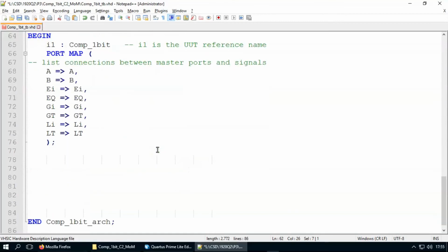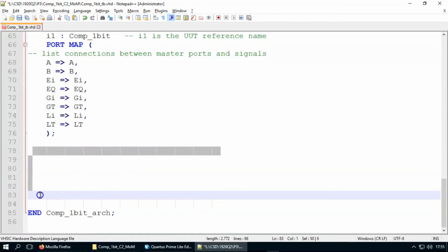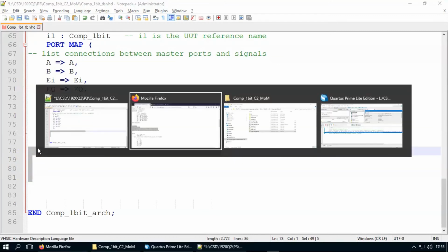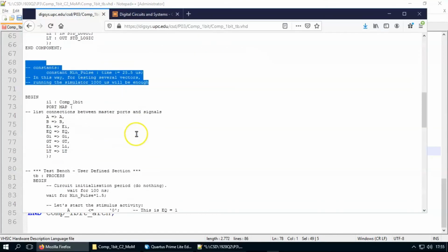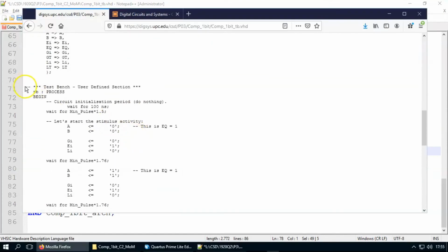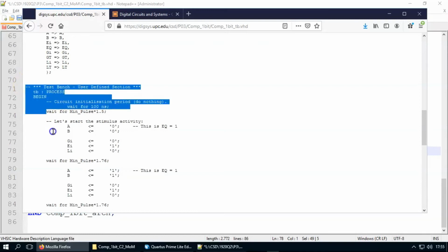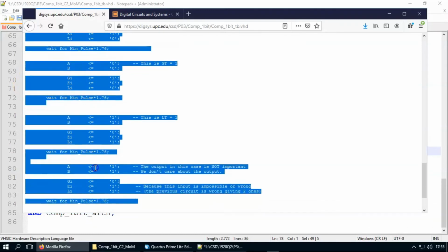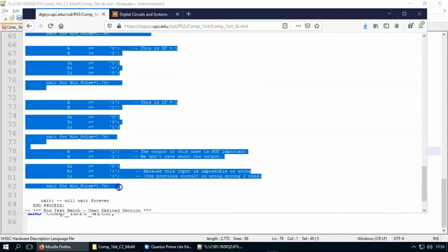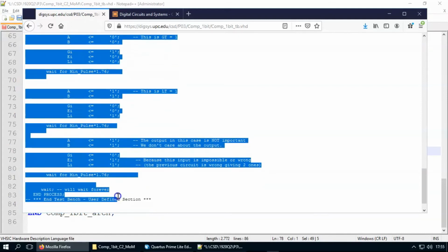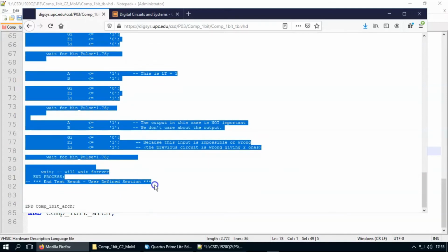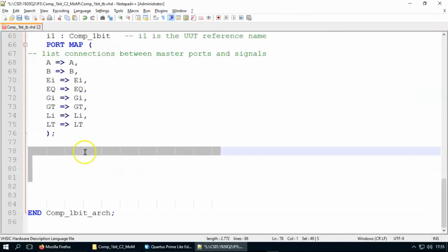And now the stimulus. The stimulus is the copying of the signals, the input signals. So you go back to the web example and you have the idea now of taking all the test bench, which has activity for all the signals, not all the vectors naturally, but some of them. So you copy all this signal, Control C, and paste it in the right place, that way.